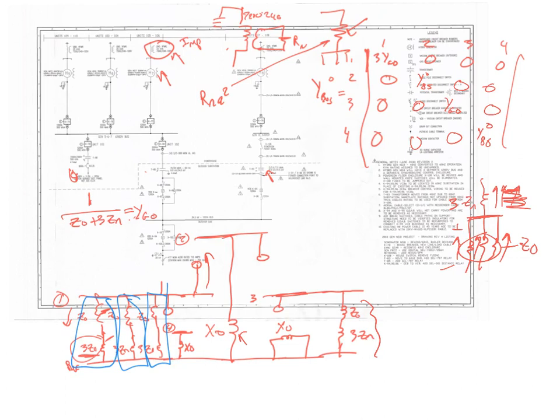So this system is well designed from a perspective of ground current, except this one here, right? Because if this generator breaker is open, so let's pretend to draw the breaker here open, bye-bye your ground reference. So this whole system right here, however long that is, that's all not protected from a ground fault. So if a ground occurs, it doesn't change anything. You don't get increased fault currents. You don't even know what happens until you close the generator, and then probably bye-bye generator. But I made that comment, and they didn't do that.